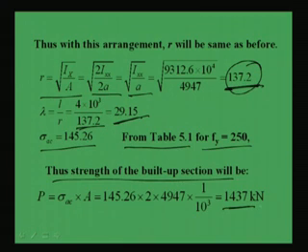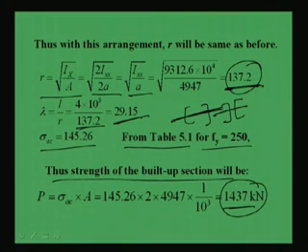See here, whatever combination we do, whether back to back or face to face, Ix will be the same for both cases, because Ix will be 2 into Ixx. So, the strength will be the same, meaning maximum strength can be attained this much. Now, if we increase the spacing, the strength about Iyy, the y direction, will be increasing, but failure will start in the x direction. But we cannot increase the strength about the x direction, because that Ix will be fixed, that is 2 into Ixx.